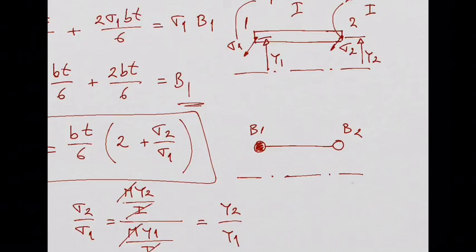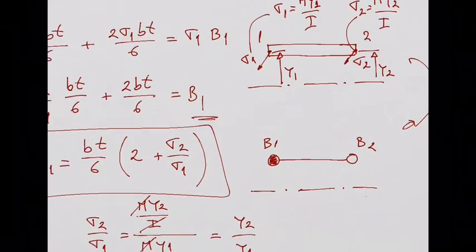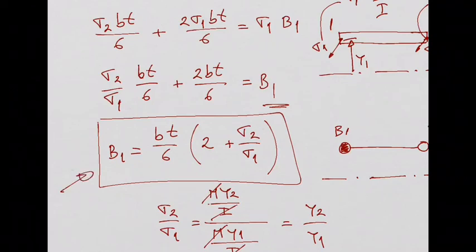If I ask you, for example, to make an idealized structure for this plate, I need to give you the configuration of this plate, right? The dimensions, the distance to the neutral axis. That is given in the question, right? So you know that. So we have everything for this equation here. We have everything to calculate the area of boom 1.